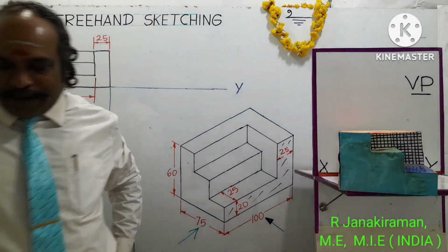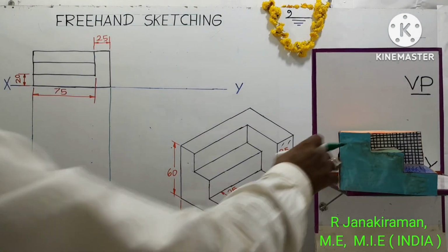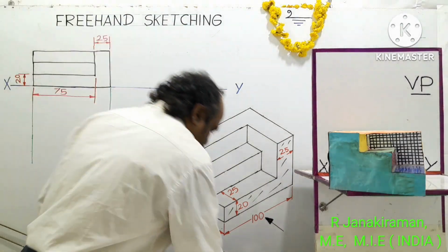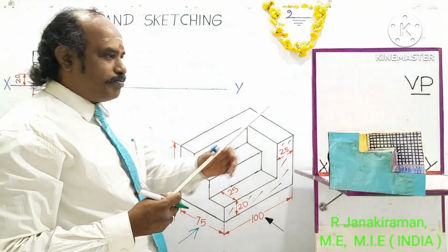Okay. So the sky blue color shall be seen, and the height of the component, height of step 1, step 2, step 3 shall be seen in this view called as a side view, that is left side view. It is to be drawn on the right side of the front view, following first angle projection principle.